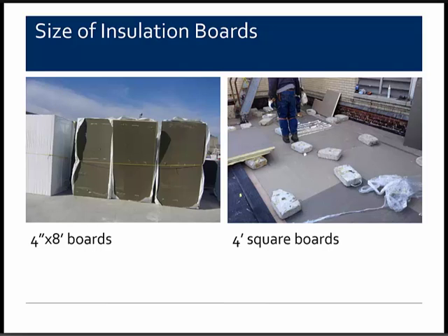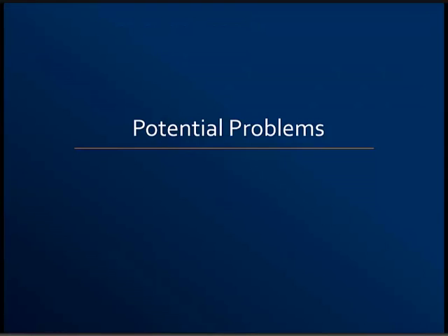One of the ideal conditions is to use a smaller board that has a smaller surface area that you're trying to bond. This is usually the better scenario of the two, where you can use the adhesive, place the 4x4 board down, and weigh it down, where the smaller board has a smaller area to contour to the deck surface that you're adhering to.